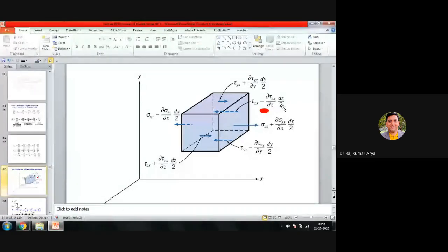Now these are the stresses, meaning force per unit area. So if you multiply by area, you will get a force. Correct or not? Yes. In this case, let's say in the x direction, the area would be this dimension and this one. Let's say this is your delta z and this is your delta y. So that is the area. So sigma xx should be multiplied by delta y, delta z, and you will get the force. Let's see what I have on the next slide. So the next slide is this.